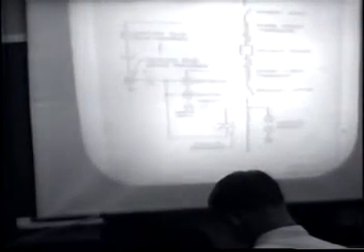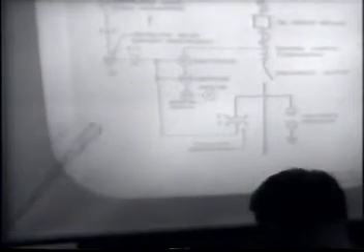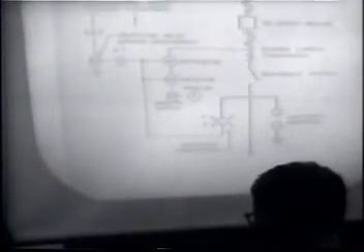So we've talked about the relaying circuit. This is the metering circuit, and we take again these reduced levels of current and voltage to feed into these instruments. They are for the function of measuring the quantities that are flowing on the circuit, current, watts and VARs, in order to give us intelligence as to what is happening on the circuit.